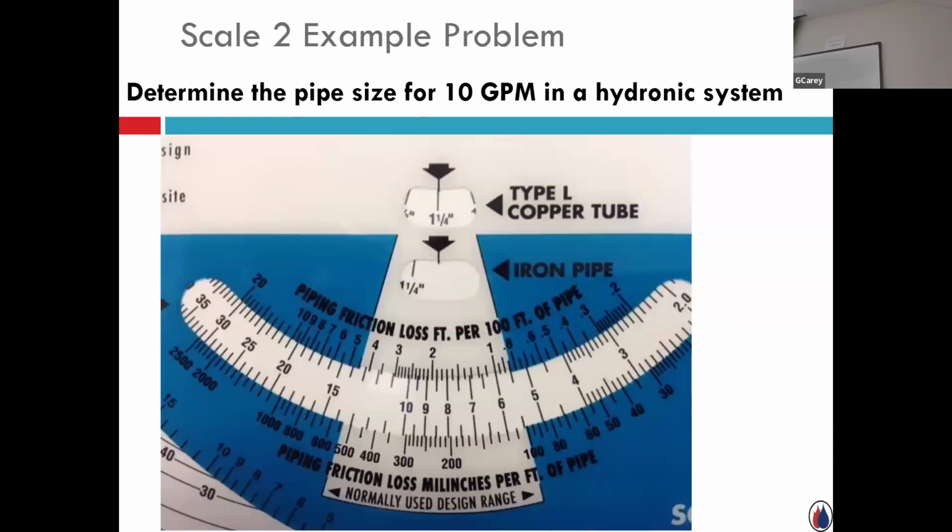So what you would do is typically, economically, the guys are trying to use the smallest diameter pipe, right? It's just less expensive, the fittings are less expensive, etc. And that's fine, but don't use too small a pipe. Excessive velocity, pressure drop's very high, so we've got to try to find, okay, what's the right size? So a lot of times they'll take that wheel and start from the smallest pipe and work their way until such time that the flow rate we're chasing falls somewhere within this white band.